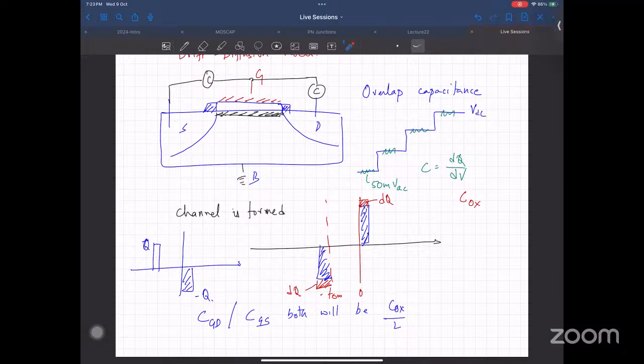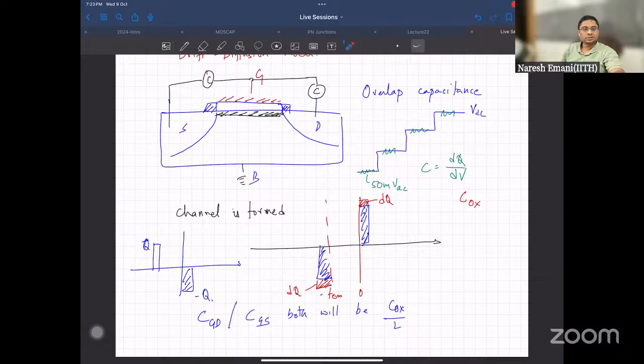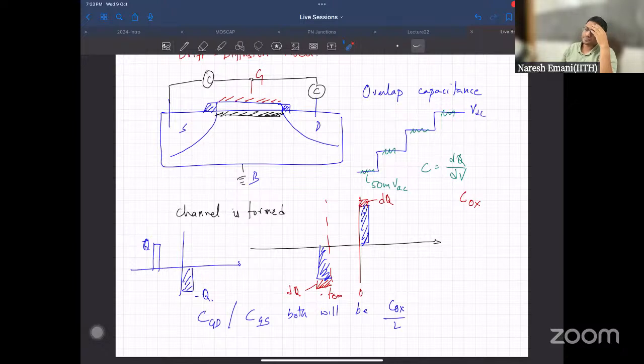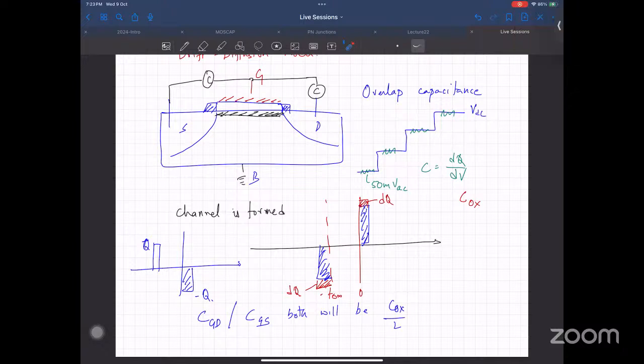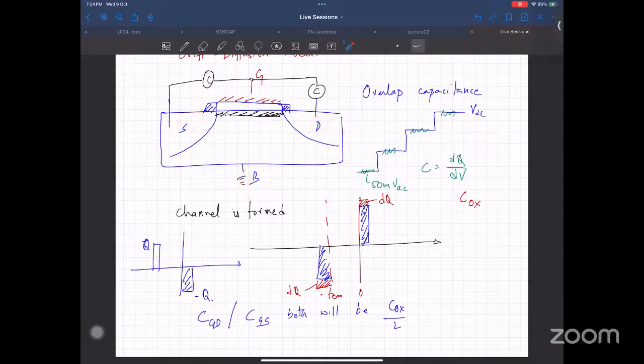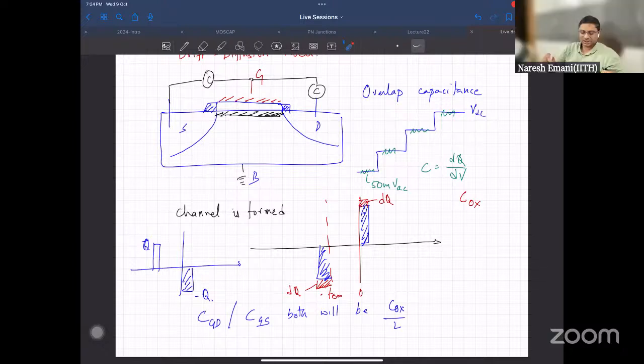But when we are getting electrons to compensate for the gate voltage, even in the case of a MOS cap, when we were trying to invert, we are getting enough electrons to compensate for the gate's positive charge. Of course. There it's simpler because you don't have the source and drain regions, right? They're only coming from here. But of course, there is a capacitance change, and then it's either HFCV or LFCV. Here also it seems we will be getting some electrons from the bulk.